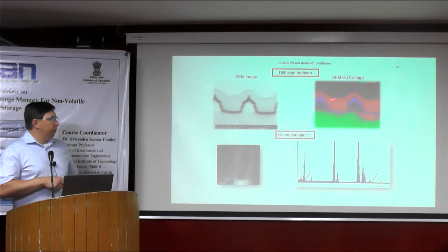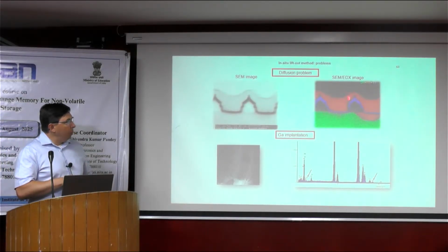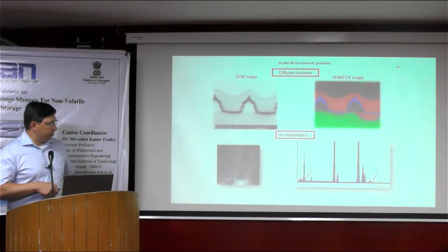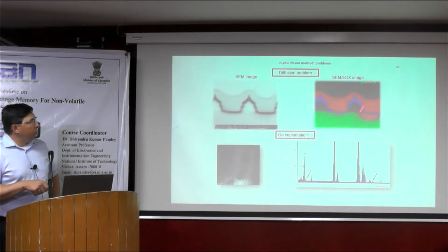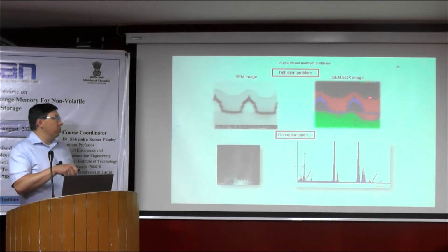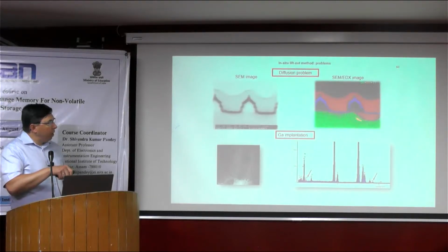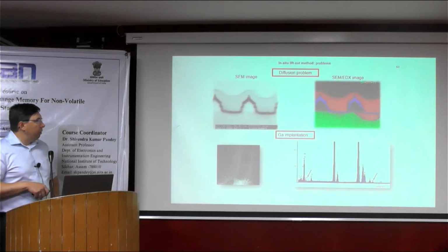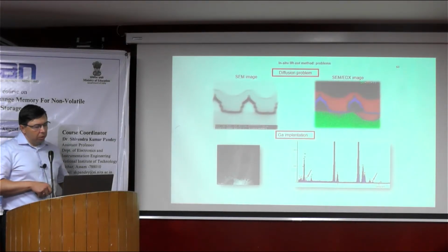So if you have a silicon, aluminum, titanium system, aluminum can diffuse through the titanium, or can be redeposited. I think it's mainly redeposition of your material on the silicon substrate, and it's a very common problem in the case of FIB.